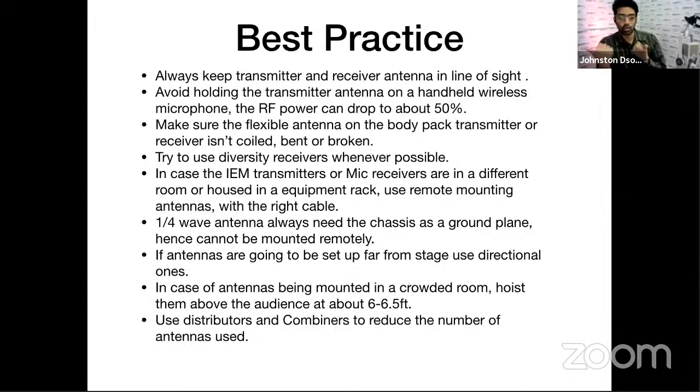Okay. Again, use distributors and combiners if at all you're using a large number of IEMs and a large number of microphones as well. That will reduce the amount of antennas you use, and at the same time, it will reduce the possibility of intermodulation happening between the antennas itself.